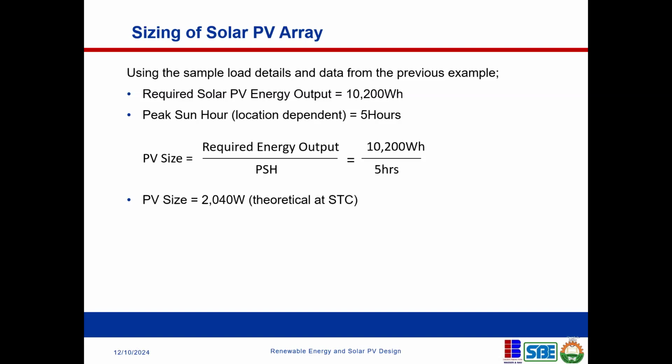I explained all of this in our first class on solar systems. It's based on the manufacturer's label, after they have subjected this PV to standard test conditions of 1000 watts per square meter, 1.5 air mass, and 25 degrees centigrade temperature. At these conditions, they obtain this value.